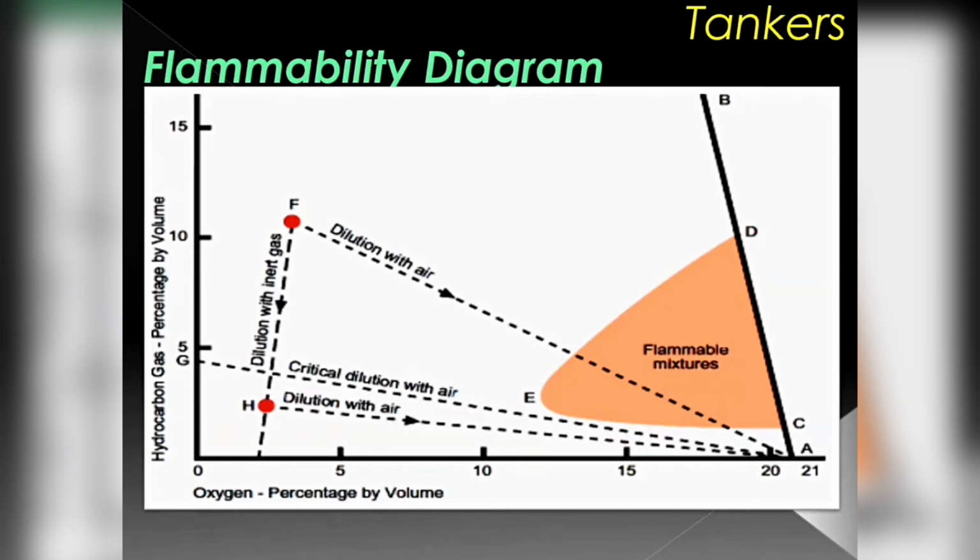But you have all kinds of people out at sea. These people think they know everything. Instead, they seal it, they close everything without inerting it back to the original safe atmosphere. They do the tank cleaning. So when you do the tank cleaning, what happens? Since you're disturbing the sludge in the tank and there is already sufficient oxygen available, the hydrocarbons are increasing in the tank. And when it is increasing, you are falling into a flammable mixture.